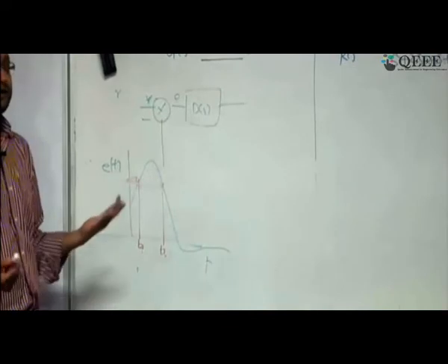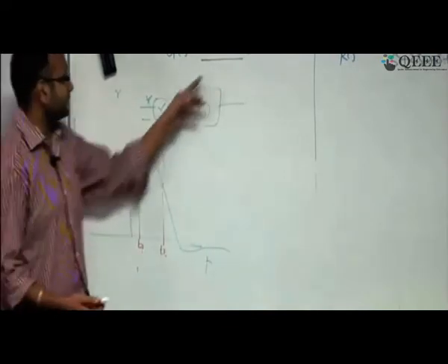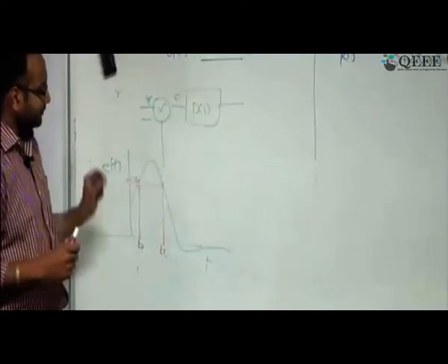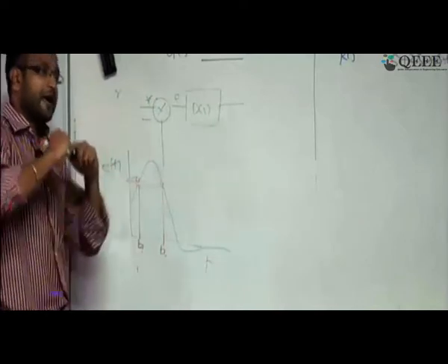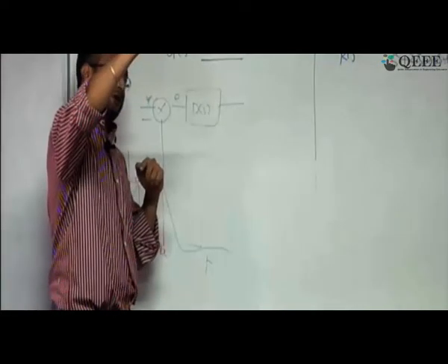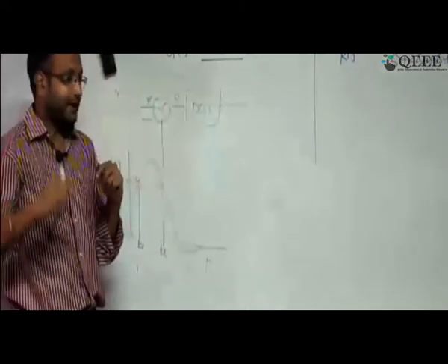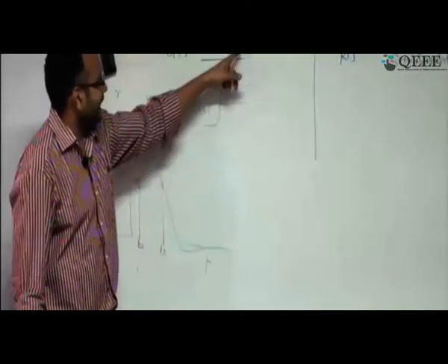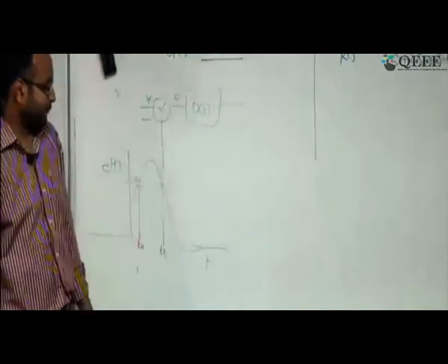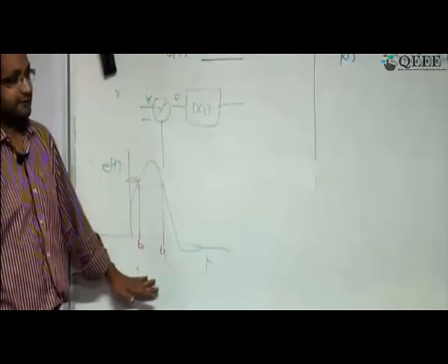one way is to introduce the derivative term. That's why we are using this derivative term, correct? This part is clear. The derivative term is used to find out the behavior of the error. If my error is increasing, you act appropriately. If my error is decreasing, you act appropriately. This is possible by adding a derivative term, and this derivative term is this part. This is the intuitive way of understanding it.